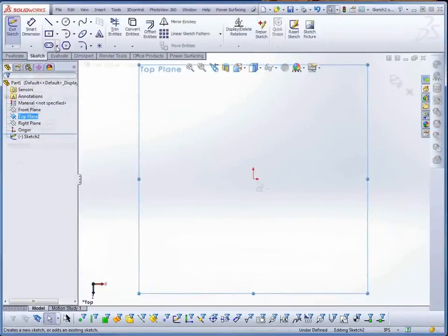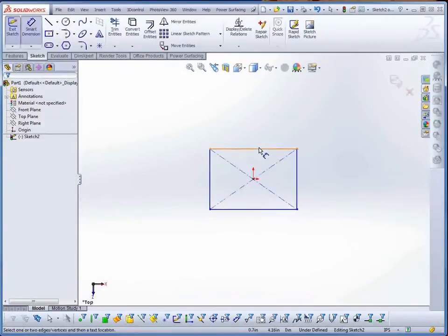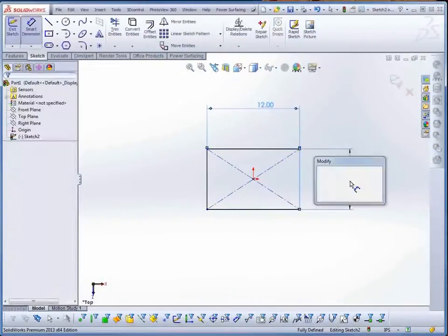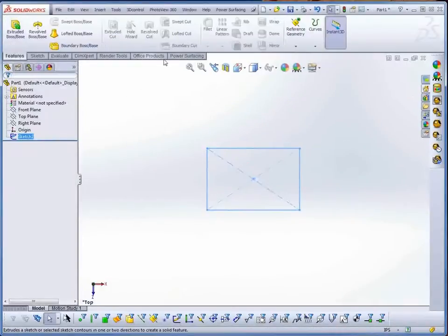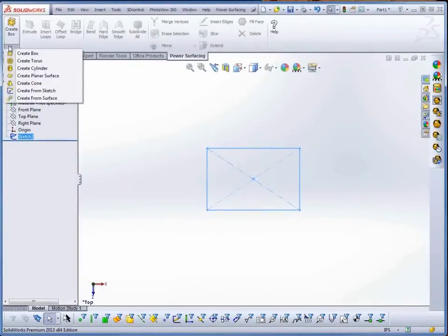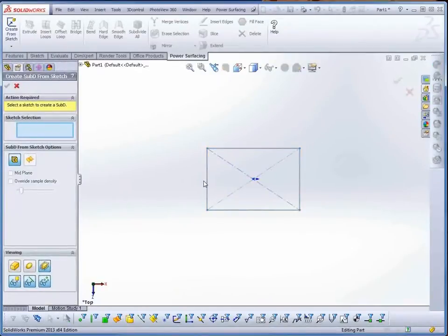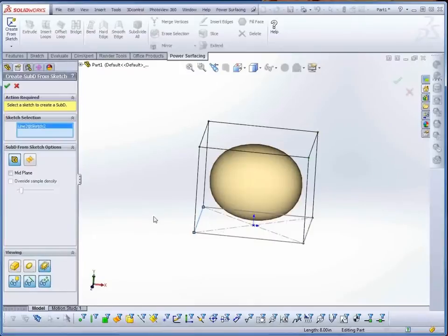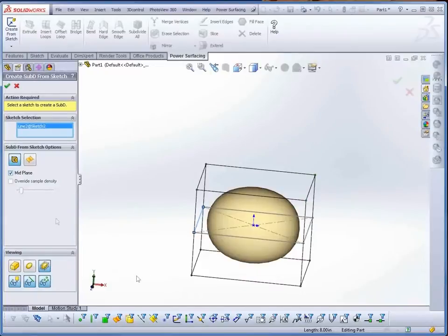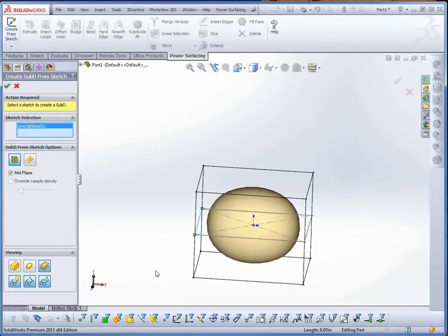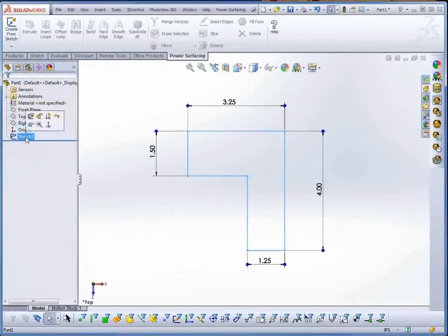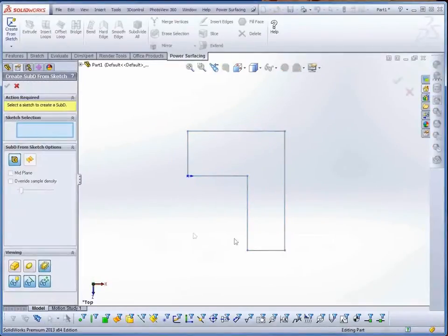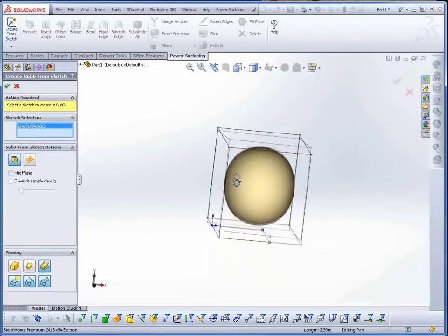A third way to start your sub-D is with the sketch. This allows you to start with a predefined location and orientation. With Create from Sketch, you have two options. As a solid, the sketch can be extruded up from its construction plane, or both directions from mid-plane. For solids, sketches over 4 sides will use only the bounding box, so keep it simple.